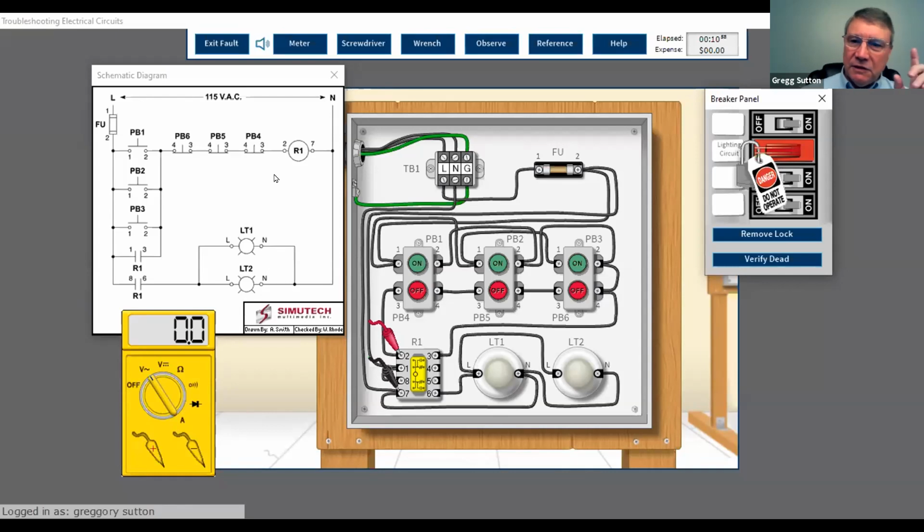Right there. It's also really good practice to take a wire off if you're going to check something like that, because you might be reading through another part of the circuit. Can you get your screwdriver? I'll unscrew the terminal for number 2. There we go. Now, can you check with your own meter across 2 and 7 and tell me what you expect? Ohms.